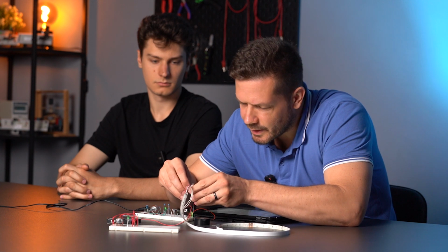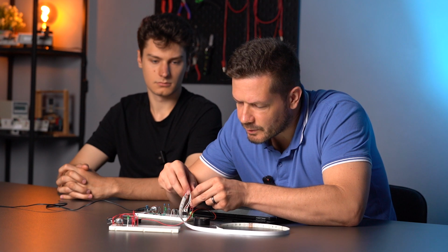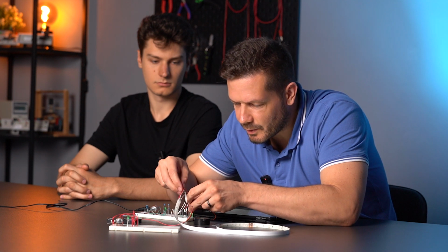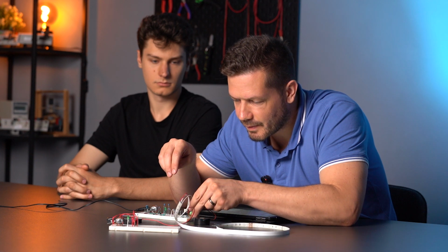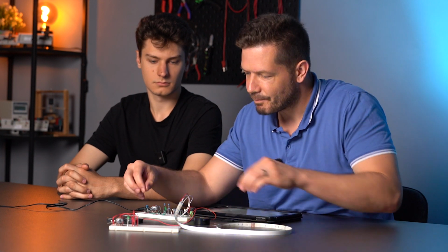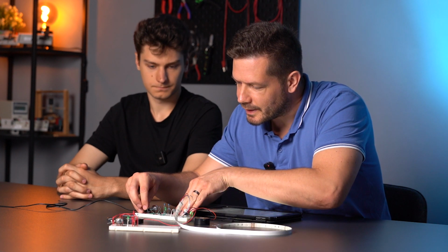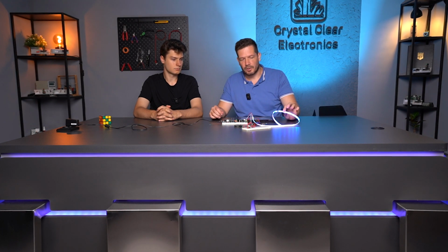So I'm gonna wire this one in now. I have to make sure that the polarity is correct. First, I connect the ground. Then I connect the positive polarity to the dotted 12-volt output. We can still see this blinking, but to make everything work properly, we know that by replacing the capacitor with a much smaller capacitor, we will get a very high frequency switched signal, so we see the light as continuous.